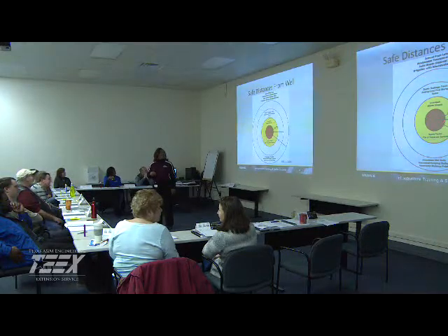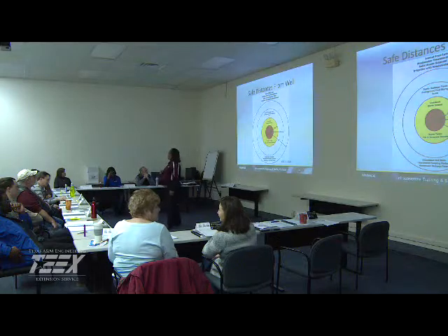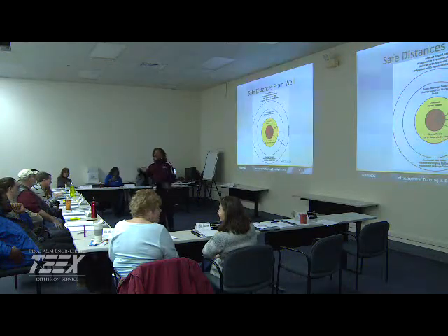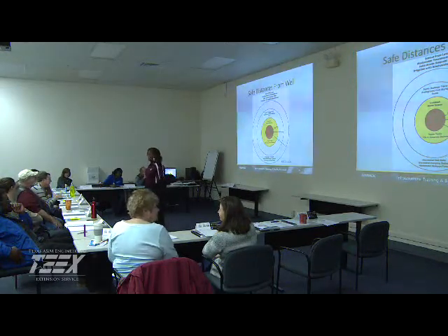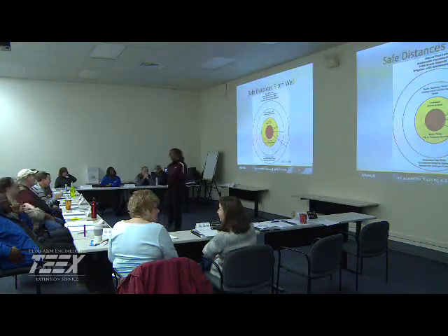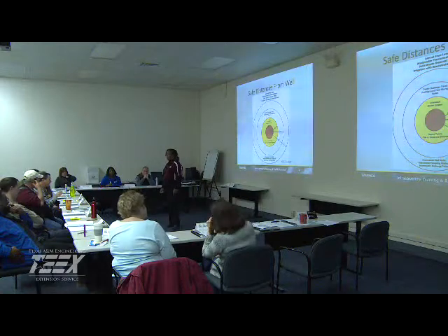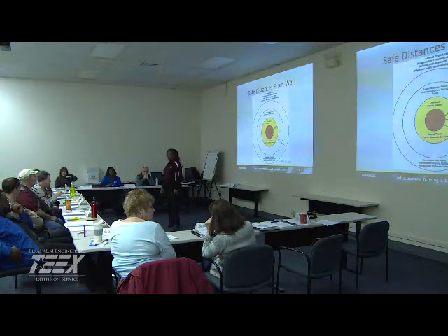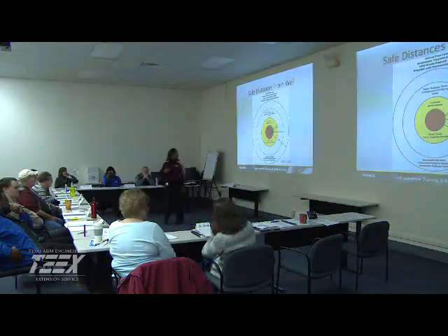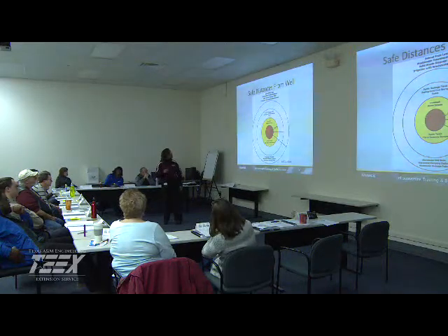Now as far as sanitation goes, safe distance from a well: there should be no source of contamination within this little red spot here. 50 feet, absolutely nothing. That's our lockdown rule. But again, each state can choose to be more stringent. You can have force mains and things like that within 50 feet if they're double encased. There are exceptions to the rules. But 50 feet, no source of contamination.